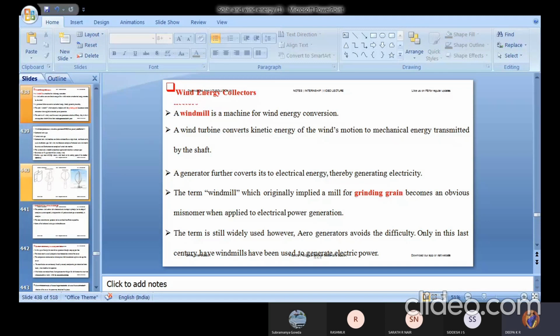Then the rotor blades are continuously flexed by unsteady aerodynamic loads. So you can see the characteristics of the blade system, how they are working. Flexed by unsteady aerodynamic, gravitational and inertial loads when the machine is in operation. Means your rotor blades are continuously experiencing all these cases. What is the unsteady aerodynamic condition? What is the gravitational force existing? Inertia of the load, all will be considered.